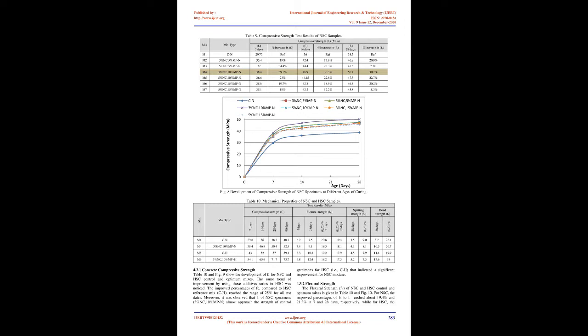3.5 Concrete mixing, casting and curing procedures. Sprinkling after stirring for NC revealed its efficiency as practical dispersion technique in mortar mixes, thus, the same procedure was applied in concrete mixes. Cement, aggregates, and MP were dry mixed in a rotary mixer for 1 minute in case of NSC. In case of HSC, SF was also dry mixed with the aforementioned mix. The remaining of the mixing water and SP were added and mixed to the previous blend for 1 minute. The ready stirred liquid was manually sprinkled during mixing into rotary mixer for additional 3 minutes to achieve the desired homogeneity. After 1 day from casting, samples were demolded and cured in tap water till the age of testing.